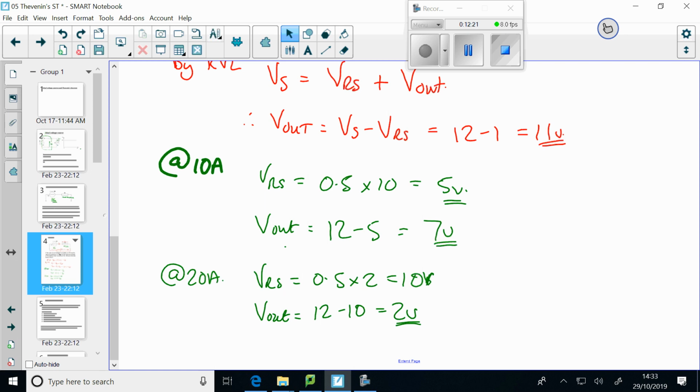We're making the assumption here that power supplies are linear in their output, which may not be the case for all power supplies, but it's good enough to do the circuit analysis that we need. The important thing to remember from this is that an ideal voltage source has an internal resistance of 0 ohms. And then we represent the real one by imagining it has a series resistance equal to its internal resistance. So, everybody happy with that representation?